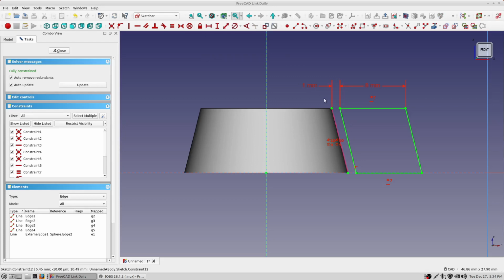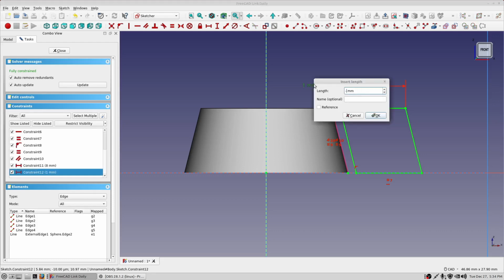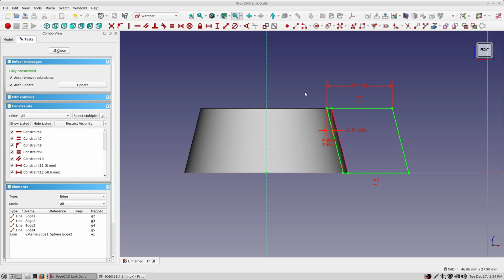And actually, because this is going to be a flat face right in here, if we just butt this up against this circular or curve, we're going to get a gap. So we actually want to make this cut into the body. So let's go up here and make this minus 0.6 to take care of that. So you see how that works. So we're done here. We've got a tab, 8 millimeters less the minus 0.6. It's registered properly. It's parallel. So we go ahead and close this out.